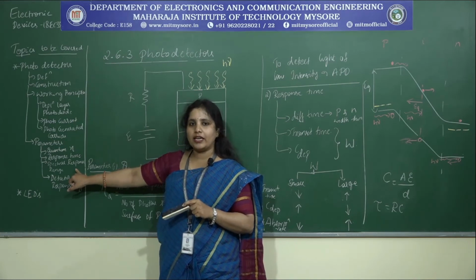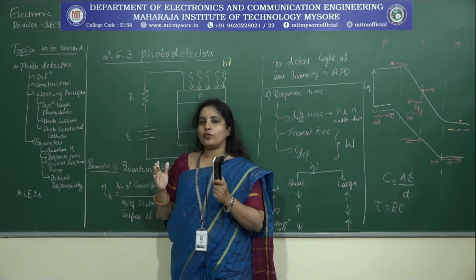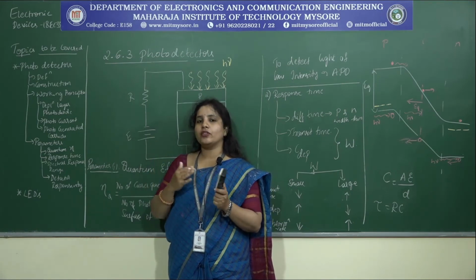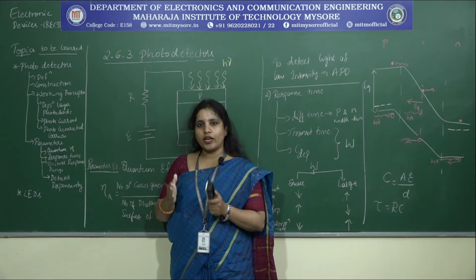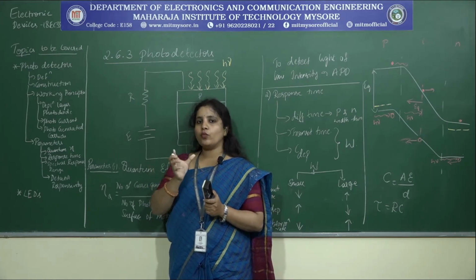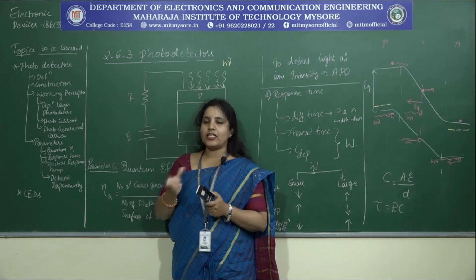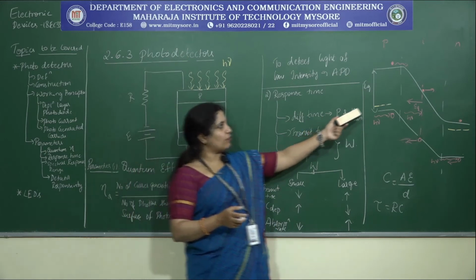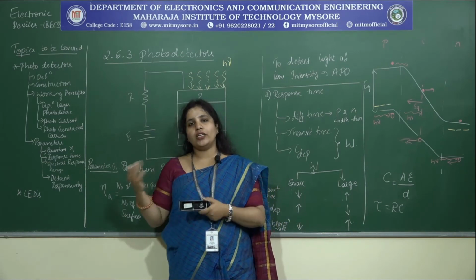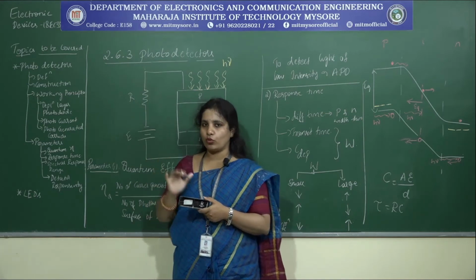Now what this basically indicates is the frequency range within which your detector can detect the light intensity. As I mentioned, your detector cannot detect light of all intensities. There is a certain range, therefore you need to ensure that if you are using a photodetector, within what range of the spectrum it can detect the light, and that is basically dependent on the Eg value that you have. Based on the Eg value, it will relate to the frequency of the light, which will in turn help you understand the range of light it can detect with the given photodetector.